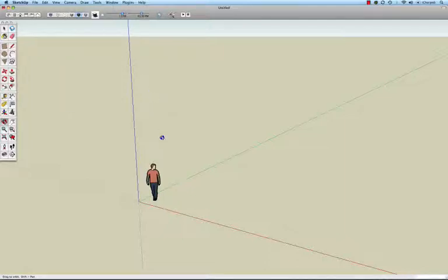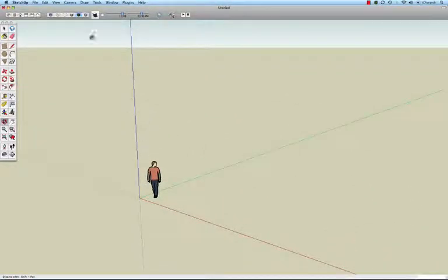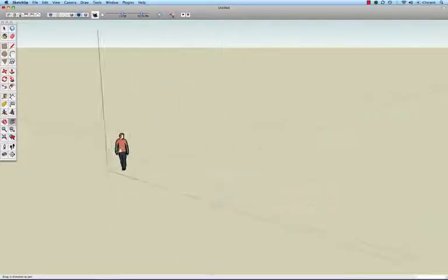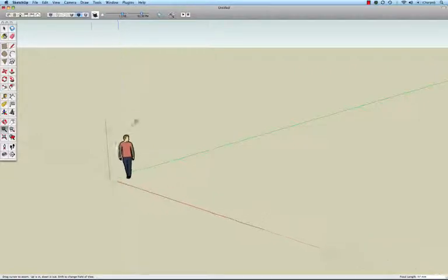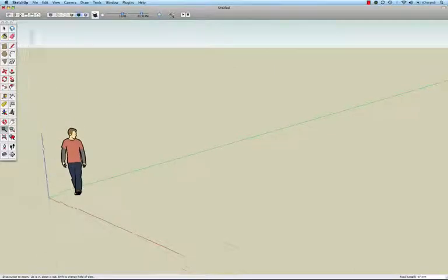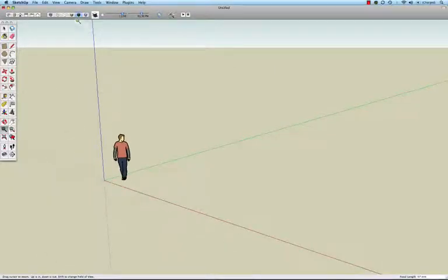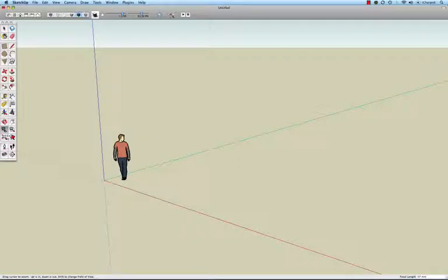As you can see from the icon there, I'm rotating in the 3D world. Go back up. Pan, the hand tool, I am panning around. Zoom, I can zoom in and out. You notice every time that I click on a tool on the toolbar, the icon also shows up actively. So this last one was zoom. I did pan, and I did orbit.